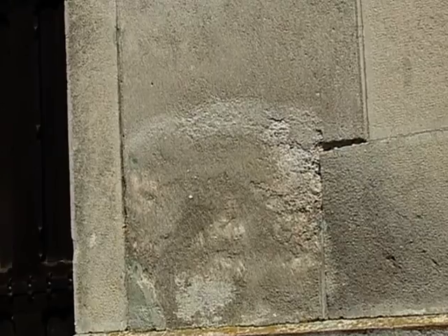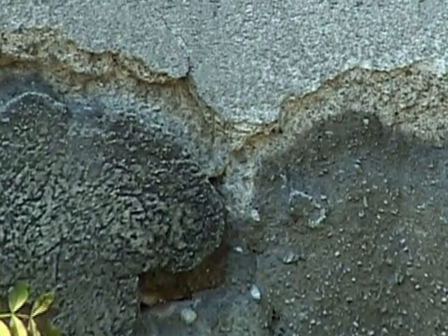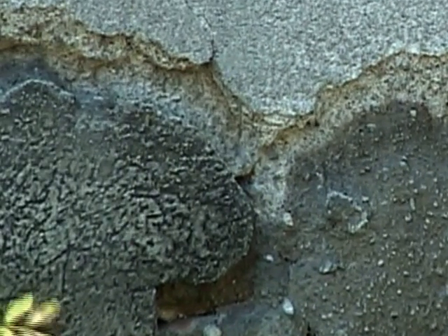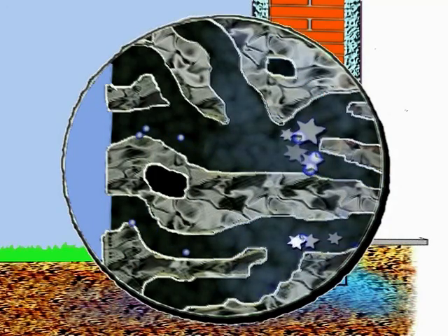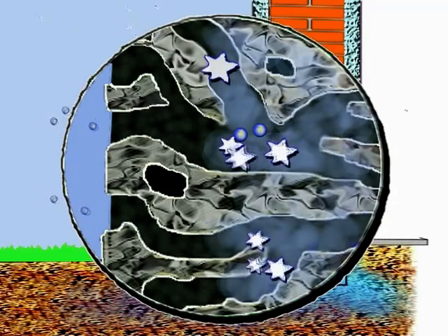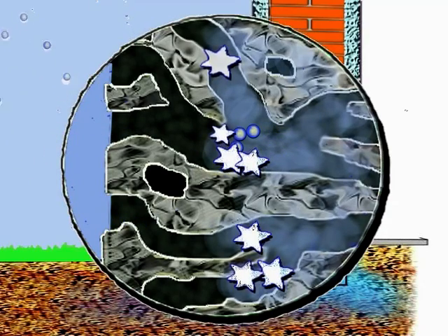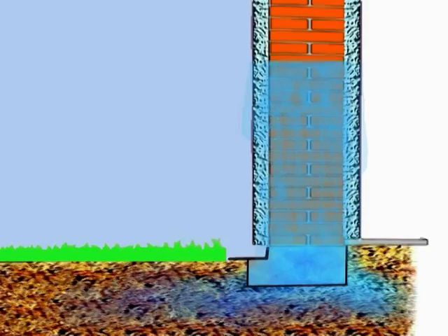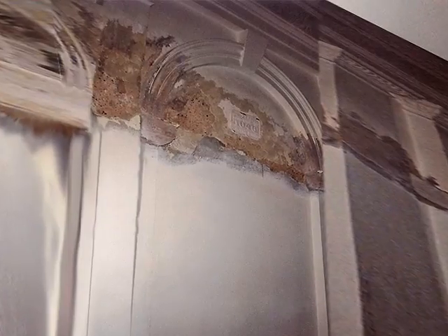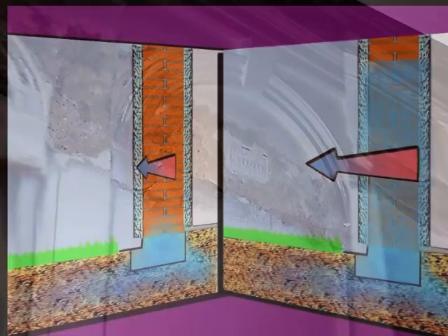In conventional plasters, salts usually rise to a visible plaster surface when they crystallize. The pressure of such crystallization and other chemical and physical mechanisms eventually destroy the plaster. In so-called renovation plasters, the aggressive salts are deposited in the lowest layer of plaster. The salts clog these pores and the plaster becomes waterproof. This makes the capillary head rise even higher and destroy further layers of plaster and wall.